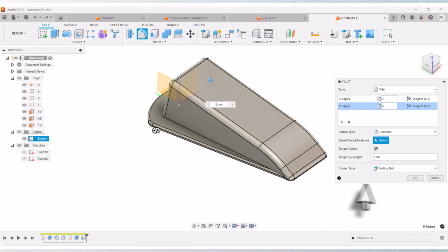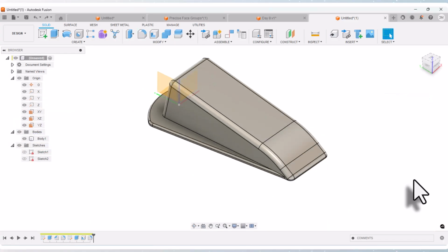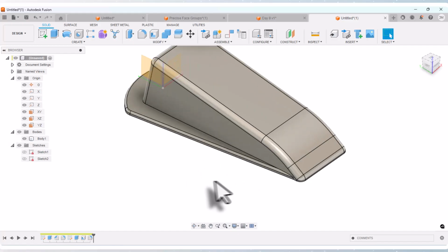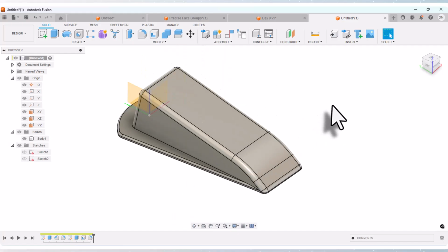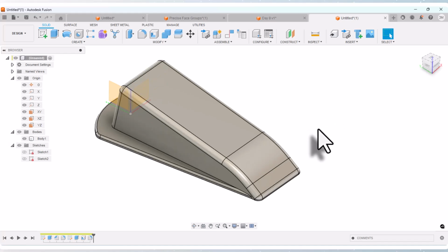And so we have those fillets in. Again, you always have to ask a question whether you want to put those 2 different sizes of fillets into one feature or whether they should be 2 separate features. Fillets can be a really problematic area in how you put them in and the order that you put them in. So just try different orders of operations to see the results that you get.